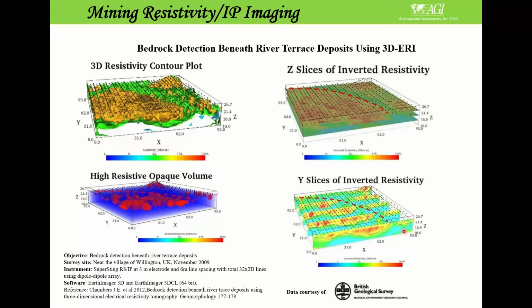So this really shows you where your unit is located, the more resistive, high resistive zone areas, and where the paleo channel is located, and then you can get this for either construction material purposes or gemstone purposes. You can get that information through doing resistivity. So in this case, you don't need to do IP studies. Resistivity will be sufficient because there will be no material to give chargeabilities, because generally you're looking for non-conductive materials.